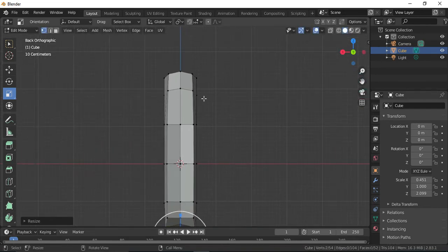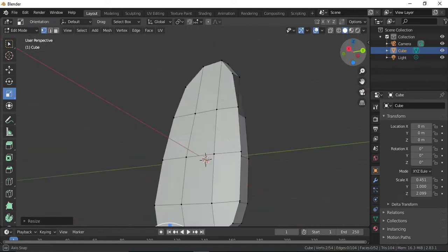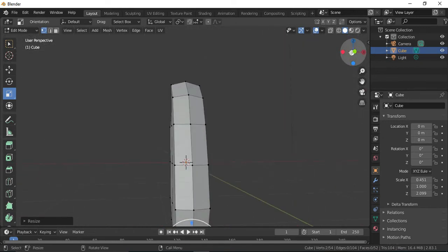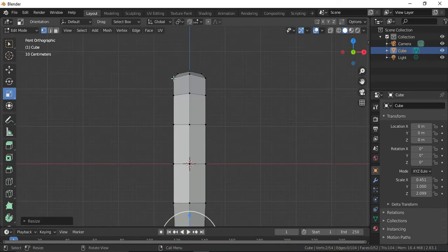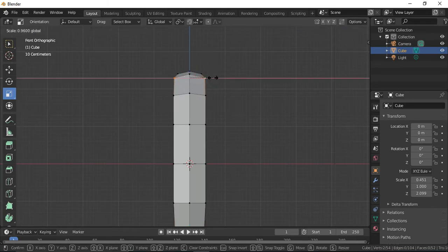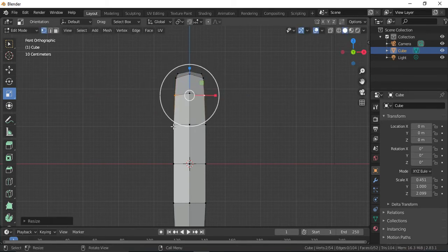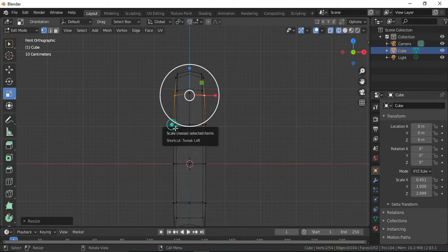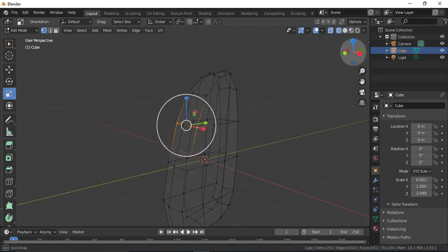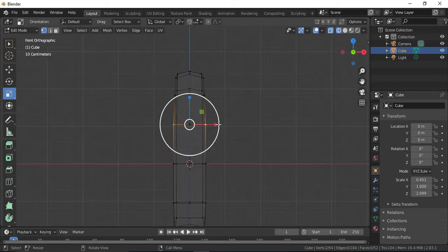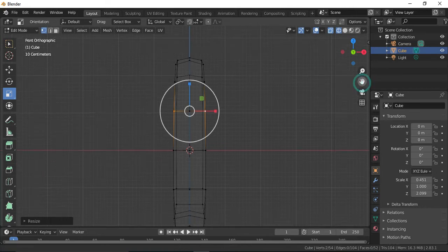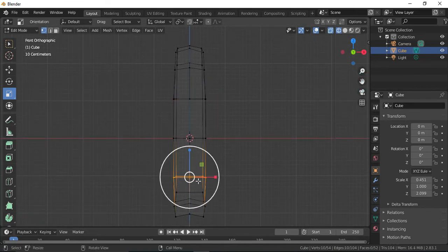All right, seems good enough so far. Let's check it from the back also once. And if I switch to wireframe view, which vertices are these ones? Correct. Only the back ones are getting selected. Or rather, I can select this entire part and squeeze it like this. Okay, careful.